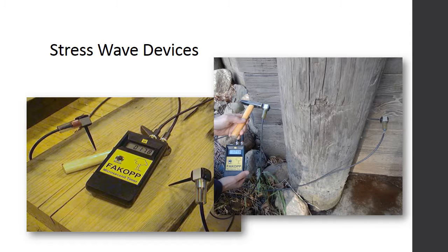One should note that many piles exhibit splits and cracks, which result in poor acoustic coupling between the transducer and the timber surface, leading to unstable readings. Multiple tests are often conducted at single cross-sections to increase the test reliability. It is possible with severe internal pile deterioration, and due to high stress wave attenuation in void spaces, that a stress wave travel time measurement may not be obtained.